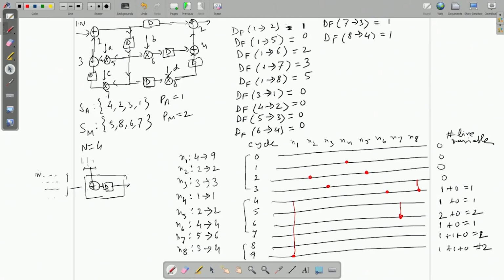So, the maximum number of live variables is 2, which means I need 2 registers R1 and R2 to carry out the storage. This is a lifetime analysis and then lifetime chart. Then we will use 2 registers R1 and R2 and follow that forward backward data allocation methodology, okay, and carry out the storage and then develop a circuit, which will be done in the next class.